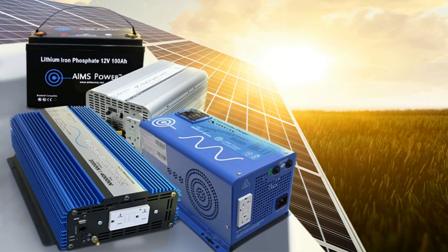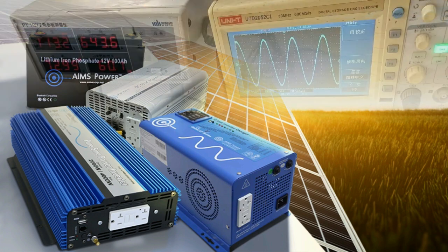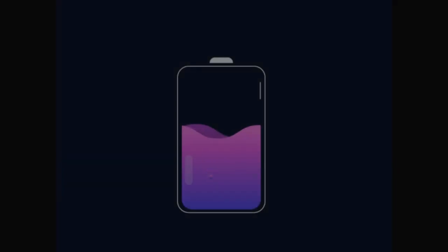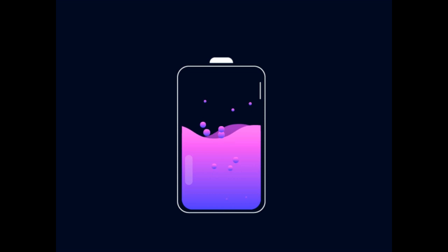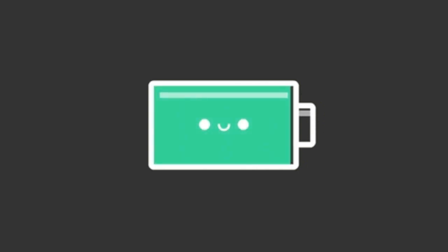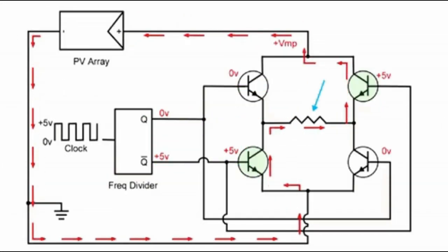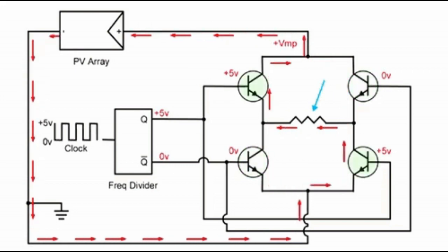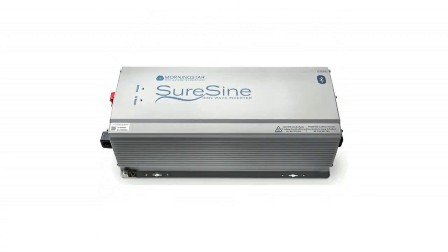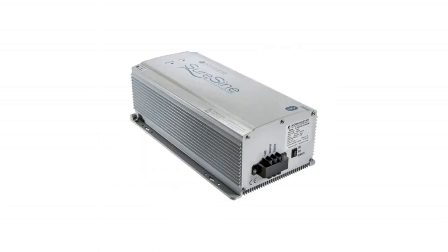No inverter is 100% efficient. At best, they come close to 92%. At worst, they can drop to 50 or 60%. An inverter needs power to operate, so expect to lose around 10 to 20 watts of power from your batteries just having the thing connected and turned on. Once it is operating, this may well increase, especially if it has to run the internal fan to keep cool. As you go up the price bracket though, some inverters have a sleep mode and will reduce their own consumption to a few milliamps until power is required.